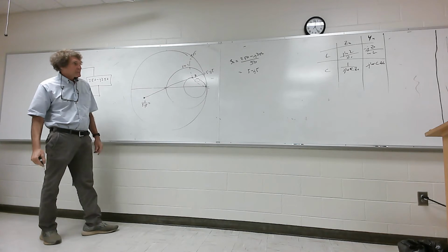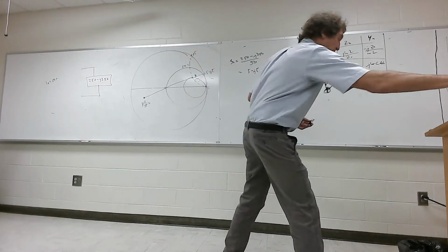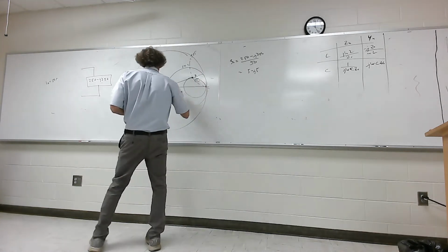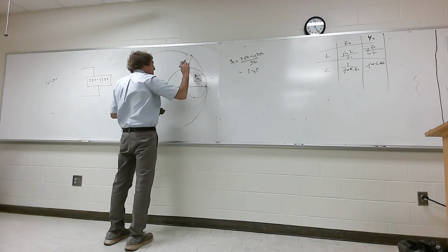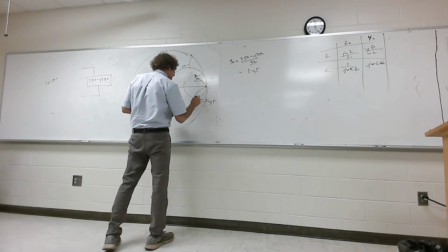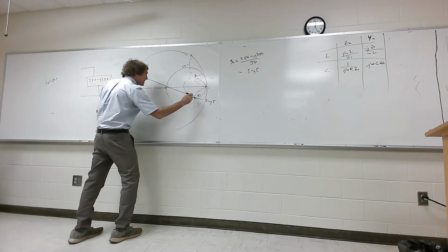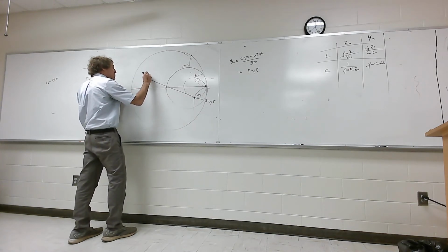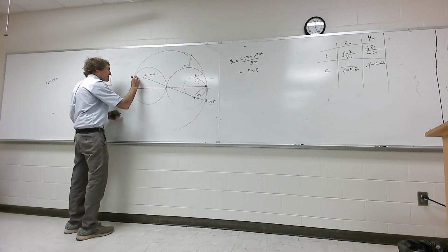Would the point you're in be on the bottom half of the Smith chart? What's that? The first point. Oh, you know what? It's on me, you're right. That's absolutely right. I have this drawn wrong. It should be down here. This is plus j5, my bad. This should be 5 minus j5 right there. And that means when I go through here, that would be my first point. My bad, it would be here. And this would be 0.1 plus j0.1. And here's my 1 circle, not drawn very well. Did you all follow me? So this is the second point. Now we've got 2 choices.